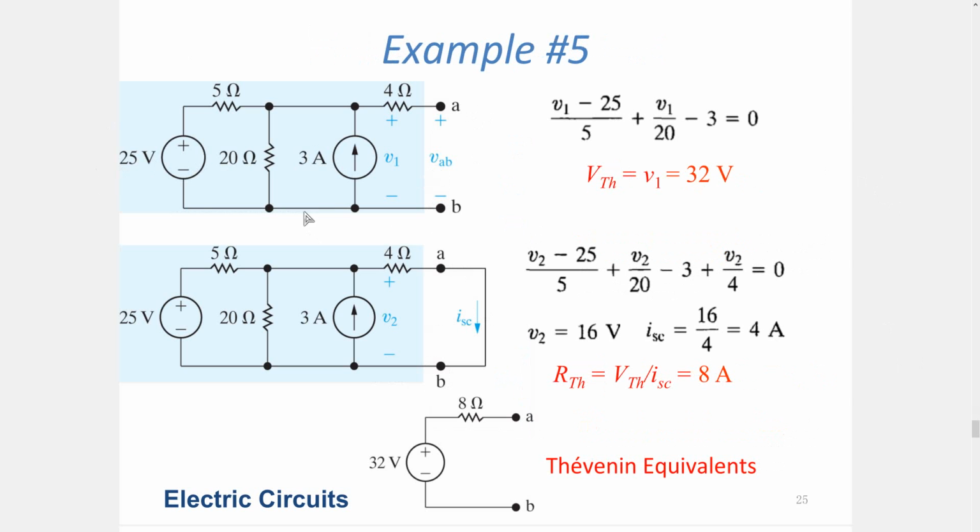Here we have a circuit. As you can see, there are two sources, one voltage and one current source, and three resistors. Now I have these terminals and I'm interested in this terminal behavior. So I want to create a simplified model of this complex circuit. I just want to learn the voltage between VA and VB, which means VA minus VB. Since VB is connected to the reference point, I'm actually interested in VA. Now, VA is connected to this circuit node. Actually, there are 2 nodes here.